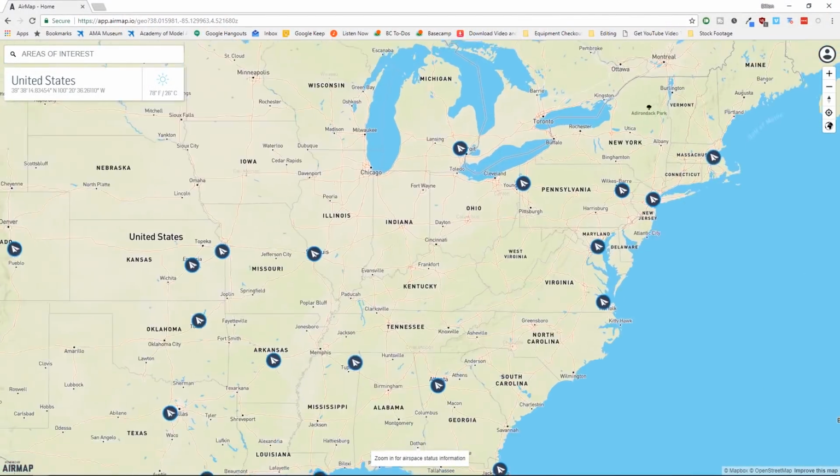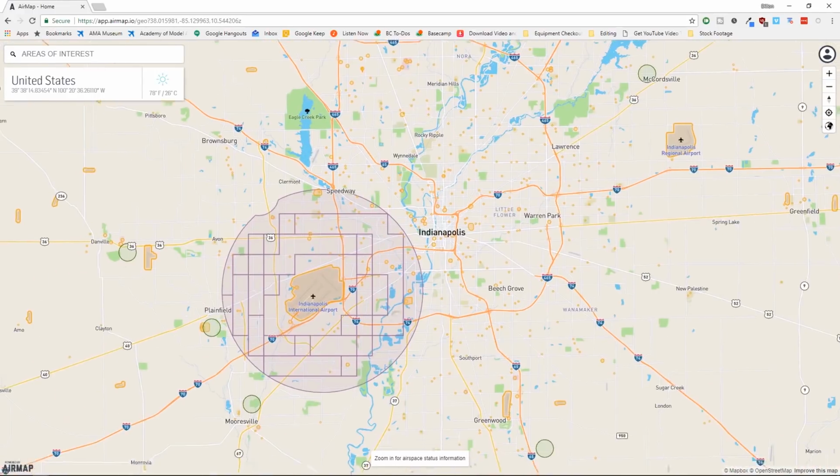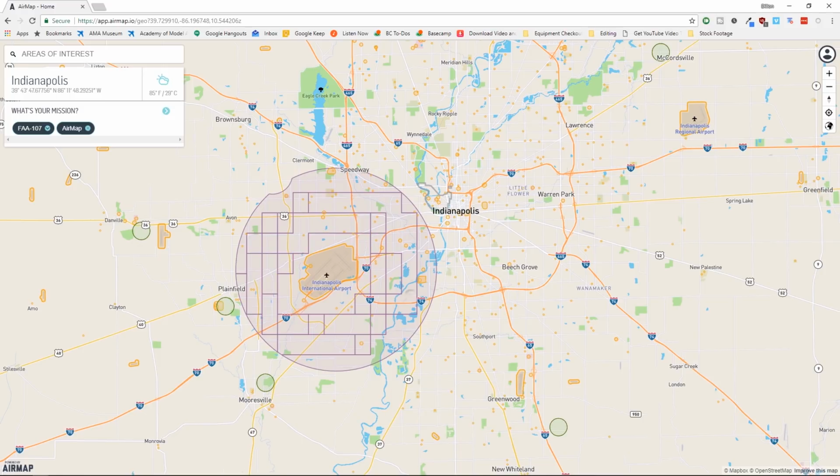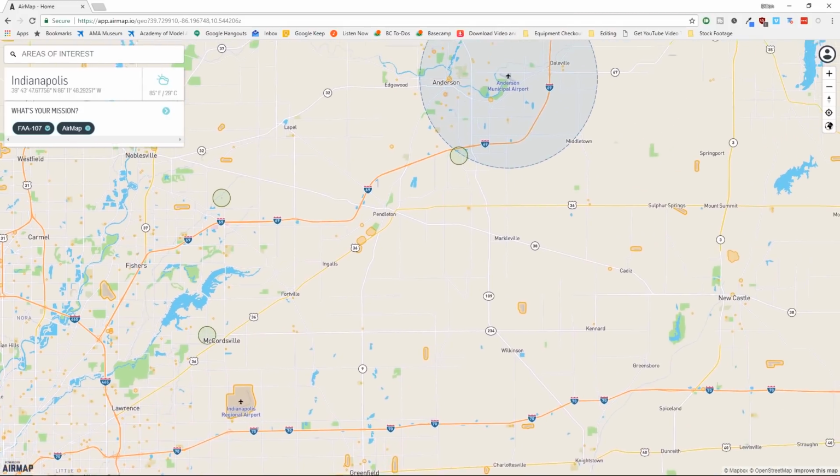Now, to help create a system that has better resolution and response time for drone pilots, the FAA began constructing what they call UAS Facility Maps, or UAS-FMs. Throughout 2017, the FAA began working with more than 500 airports across the country to conduct a detailed analysis of where drones could safely operate within controlled airspace. The FAA reasoned that just because you don't want a Cessna 172 barreling through a particular patch of sky at 120 knots unannounced, doesn't mean that a drone couldn't safely conduct a roof inspection at 75 feet above ground level in the same area, provided air traffic control were aware of it.